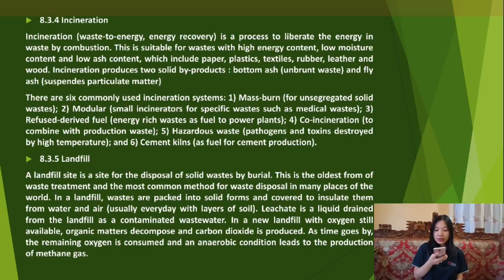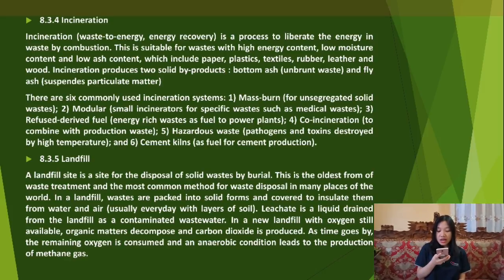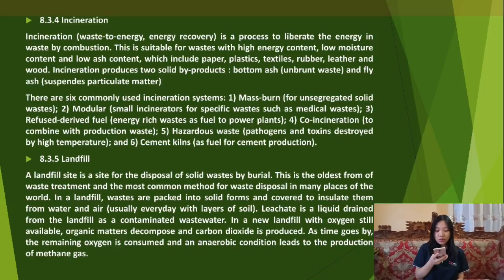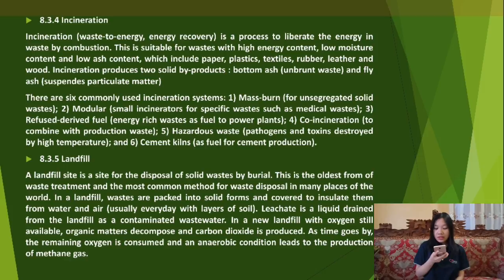Leachate is a liquid drained from the landfill as a contaminated wastewater. In a new landfill with oxygen still available, organic matter decomposes and carbon dioxide is produced. As time goes by, the remaining oxygen is consumed and an anaerobic condition leads to the production of methane gas.